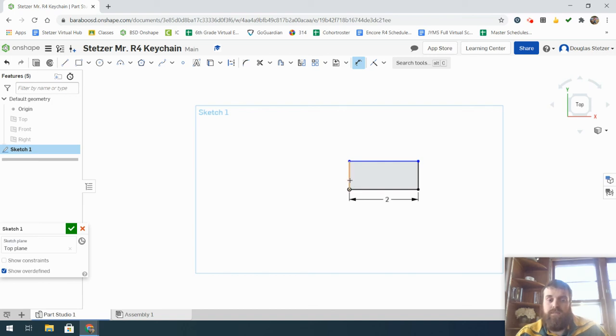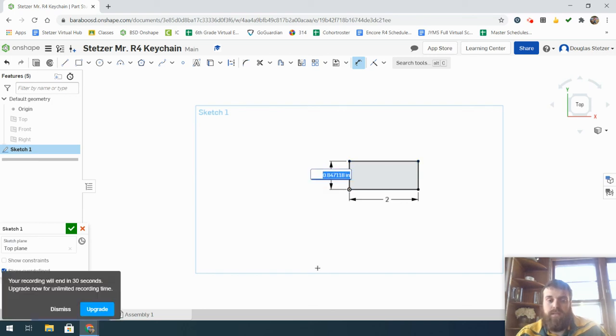So I'm going to click on a vertical. I'm going to use the vertical left line. I'm going to move my cursor out. I'm not moving it far, just a little bit. And then I'm going to set this distance to 7/8. Enter. You can use fractions or decimals. It will change these and adapt them to our decimal system. It does not matter how many decimals you see. It will be exact. This is just showing you what that reference point is.